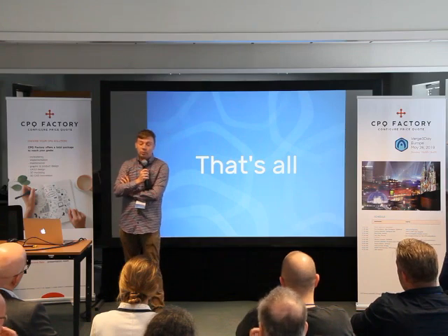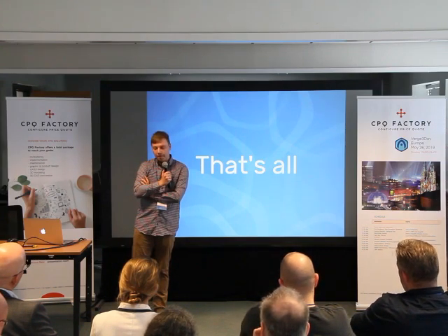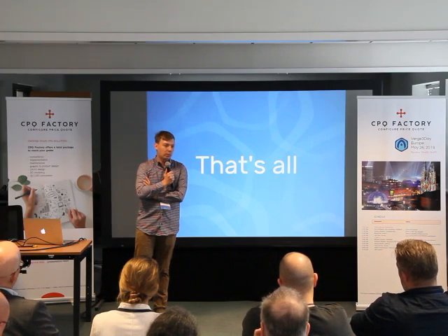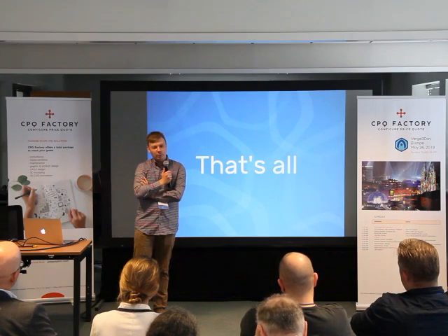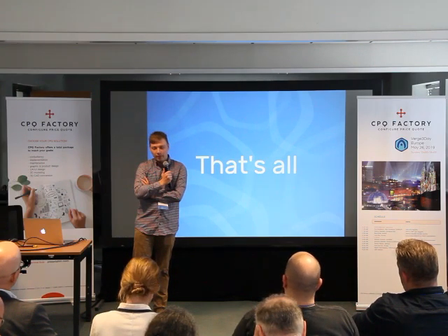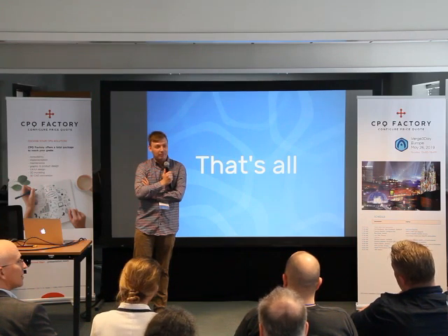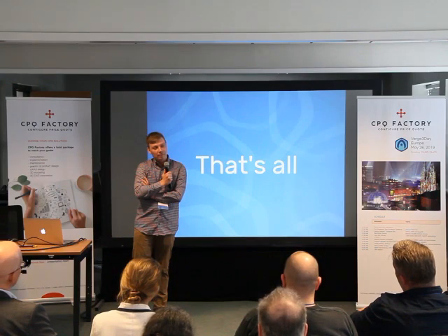I use a lot of modifiers when I'm modeling, when I'm preparing a model, but before I export, I prefer to bake them, to apply them before exporting, because it will give you a stable result. It's already like a golden rule. You don't want the mesh to get all mashed up.